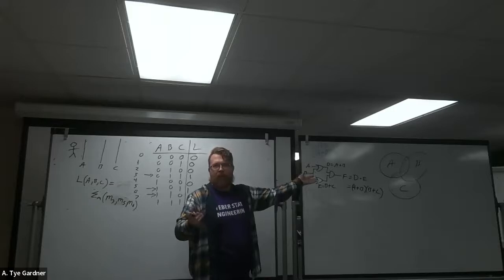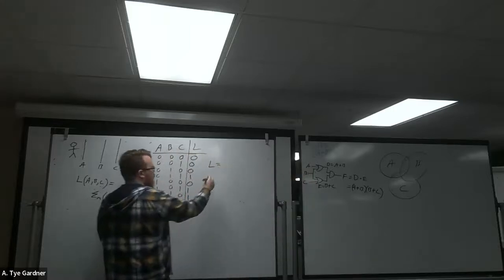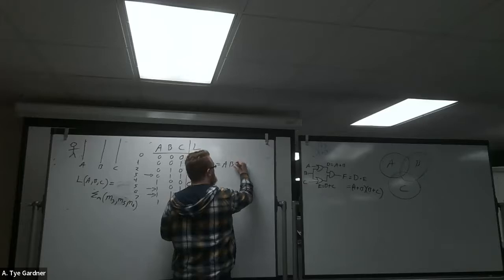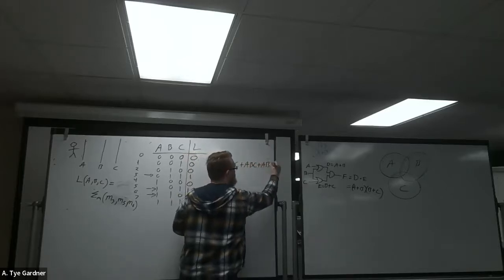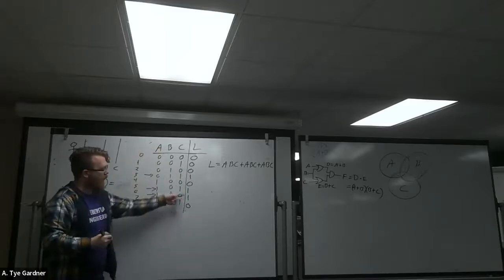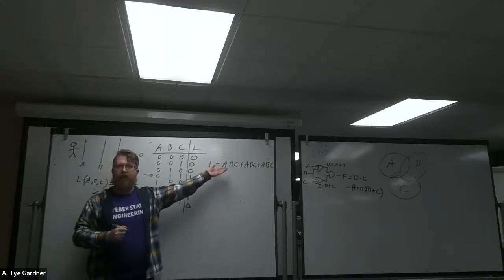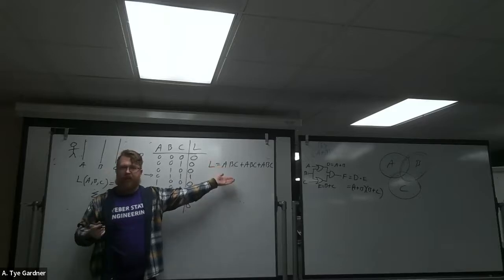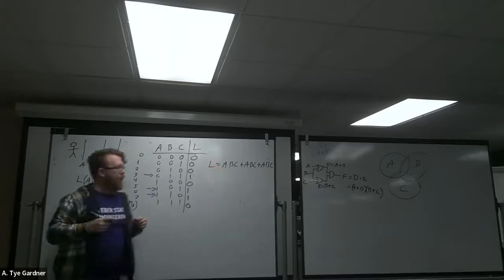But it's just going to give me a sum of products, it turns out, where L is equal to... I have 3 minterms, so I have 3 1s. I'm going to put up 3 minterms. All of my minterms have every single variable in it. In this case, I have 3 variables, A, B, and C. And now I just go look where the zeros are.